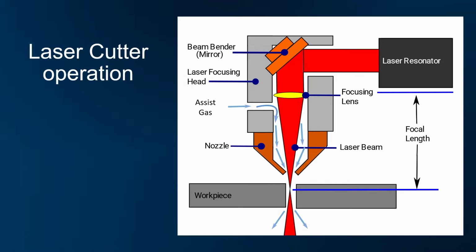Now, there's a variety of materials you can cut, and in addition to the laser doing its work, once the laser has blasted the material, ideally you would like to clear that material out of the work area, because if the laser is spending all of its time cutting essentially the dust, then you're not actually cutting on the workpiece. So you will have an assist gas. Now for your hobbyist, the assist gas is basically going to be air. It's either provided by a fan or air compressor located inside the machines. If you have a bigger machine, there might be an external air compressor giving assist gas. But yeah, so that's it, really straightforward. Make thing hot, make it burn, make it evaporate, have an exhaust fan that sucks all the mess out, and you make a design.